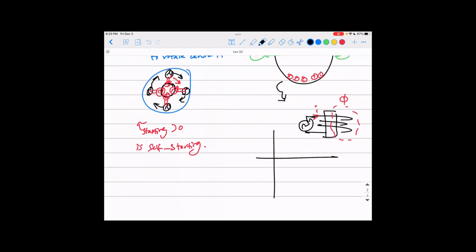Let me have a look here. That is the current versus time, okay? And this current will be a sinusoidal wave like this. It's not perfect, but yeah. The magnetic field that will be produced from this will also look sinusoidal like that, okay? It will also change with the change in the current, because the magnetic field depends on the current that's moving inside this winding. Okay, guys? Or these coils, whatever it is.